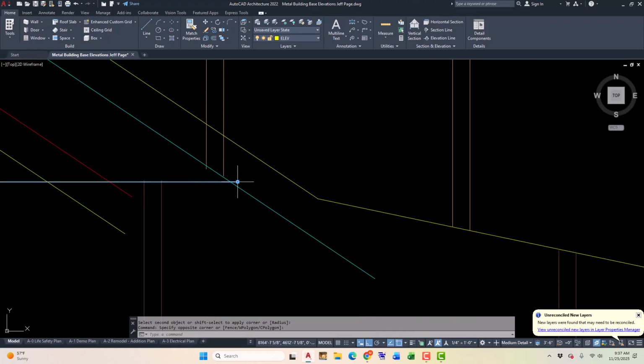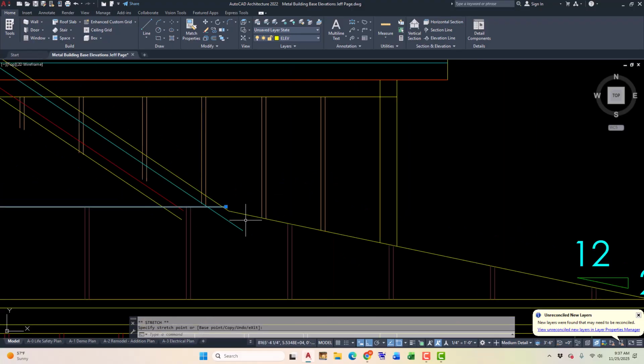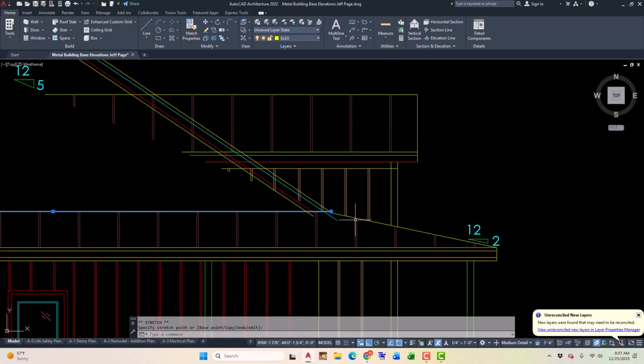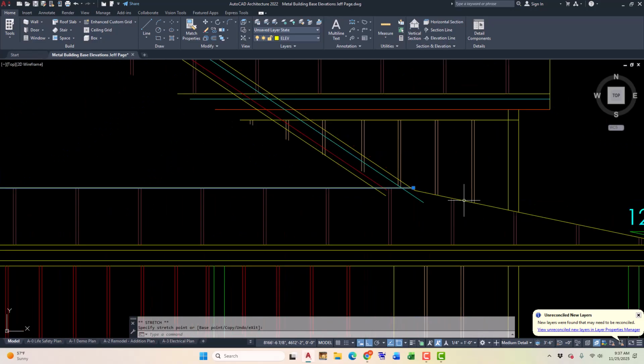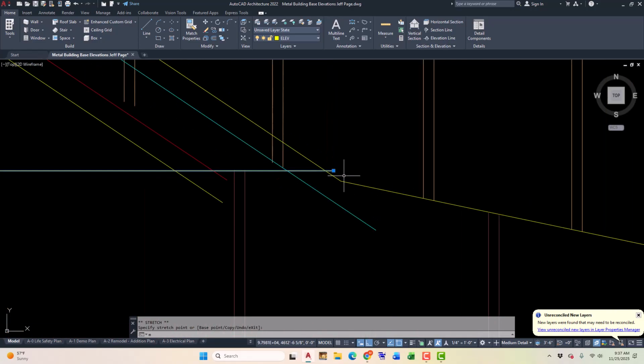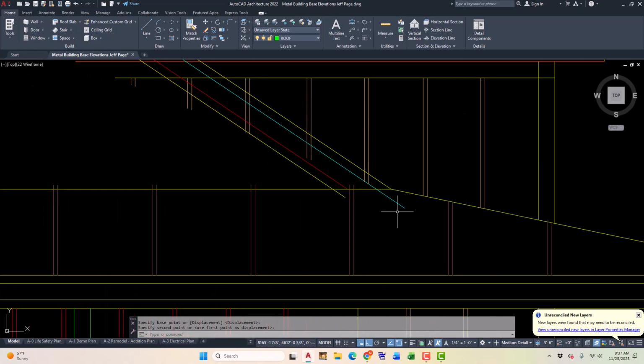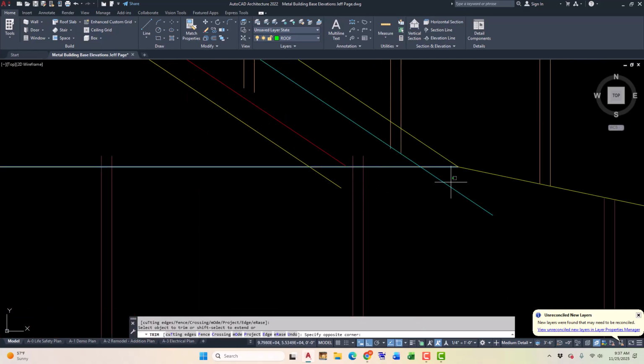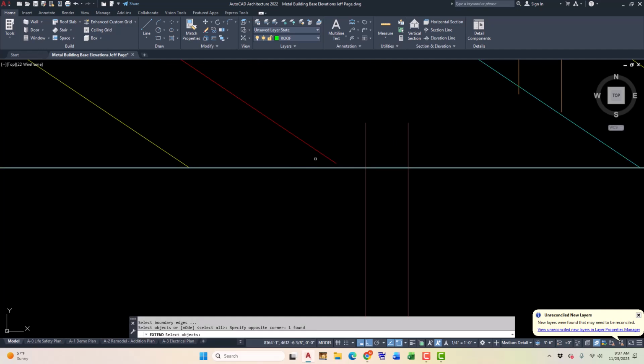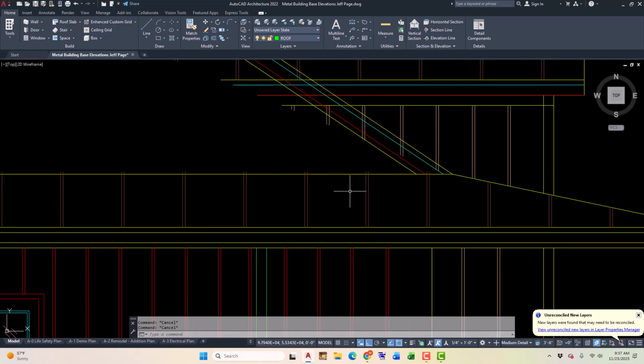Now the one thing that it does do is it creates this off looking piece, and if my roof is genuinely the same, then I would need to adjust this because that's where it's going to hit because of this roof pitch. And so then I would just use my trim command to trim out the rake trim, extend on this one. And then with the trim command, there's also an aspect of it that's called the fence setting.